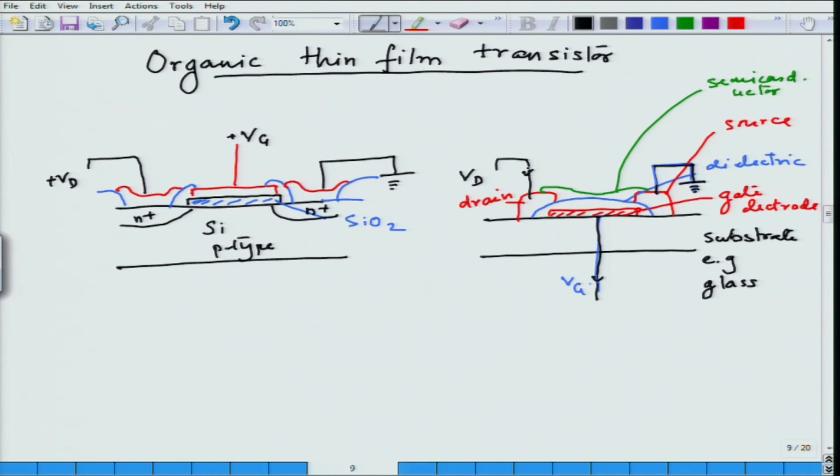So, what I have done here is, I have not started with silicon. Just by using thin film deposition techniques, I have created a transistor, which is what we call a field effect transistor, and I have created a gate effect between the dielectric and the semiconductor here. So, this is how we go from MOSFET to thin film transistor, and a very common example for thin film transistor is amorphous silicon semiconductor based thin film transistors.